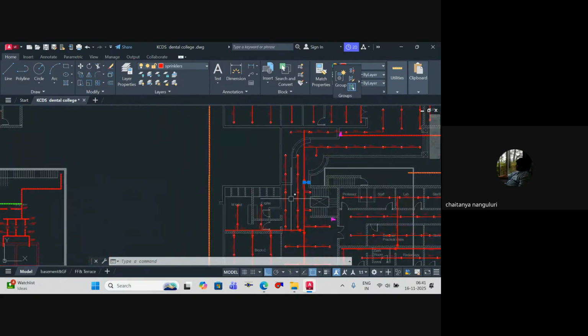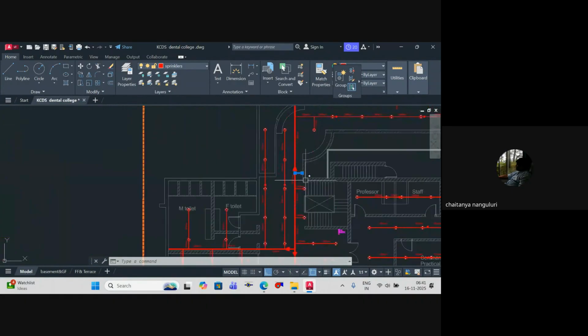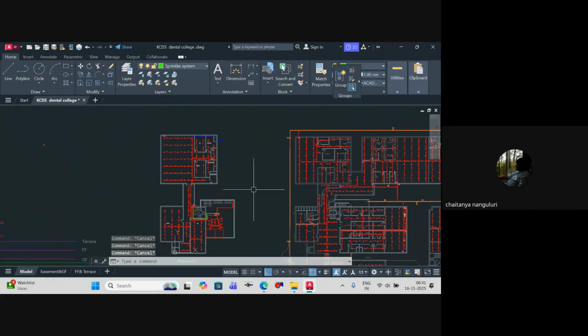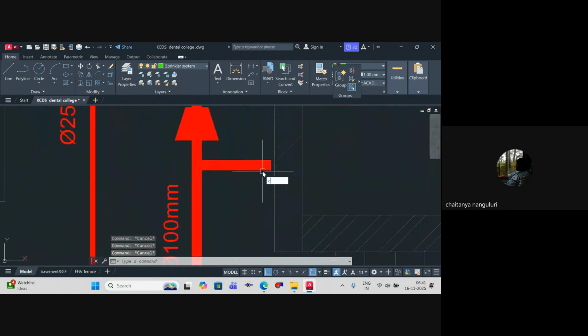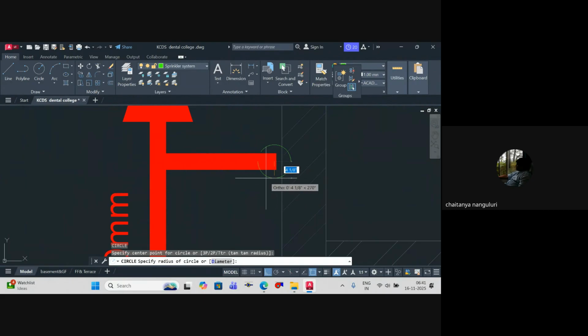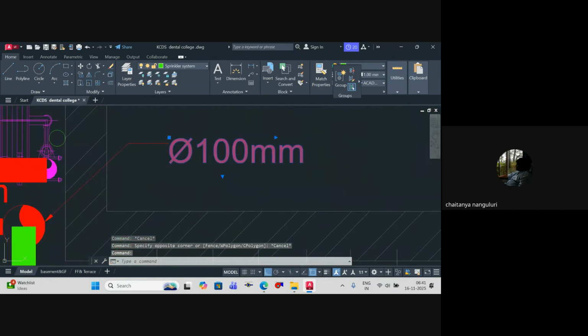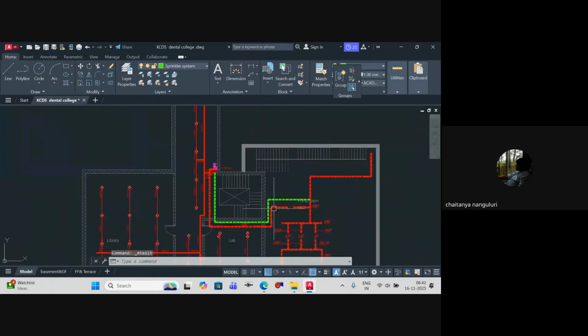And then we have a connection to this as well. So here we have it. From this external, this and this is the same line, right? So this pipe itself will reach above the floor and then reach till this point, and then you have a connection with the sprinkler system. You agree? This diameter we'll take as 150 mm or so in this case, because it's coming from below to above. According to the number of sprinklers, we have taken this.